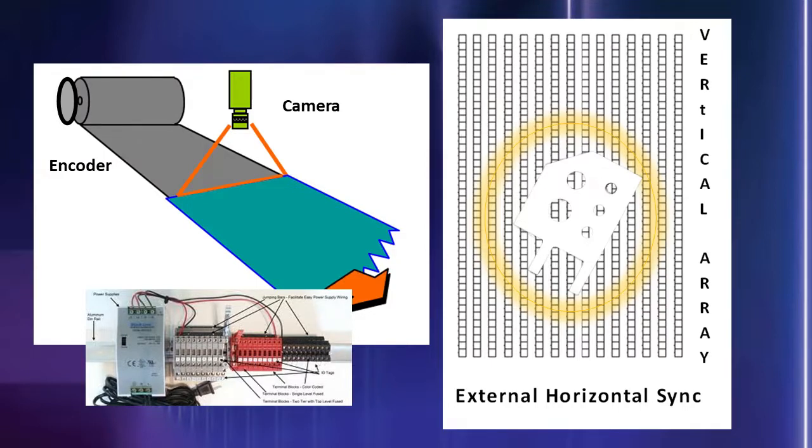The height of the image is determined by the length of the sensor array, and the width is determined by the number and spacing of the lines, which are determined by pulses from an encoder or a controller. A typical linear array is 1 pixel by 8,000 pixels, with lengths of 16,000 or more increasingly common. These long sensors usually require a larger format f-mount lens.